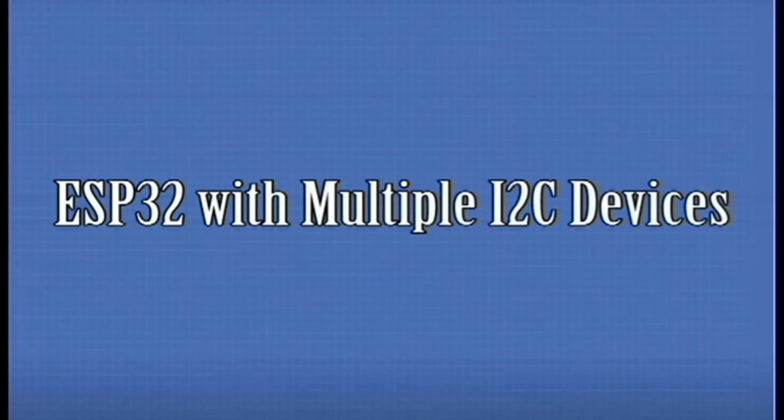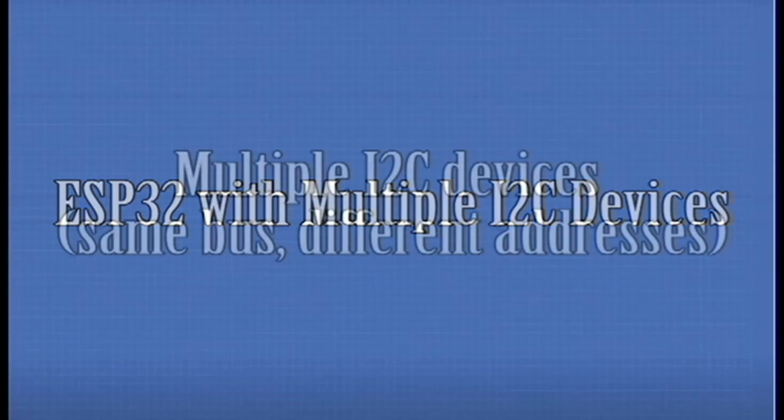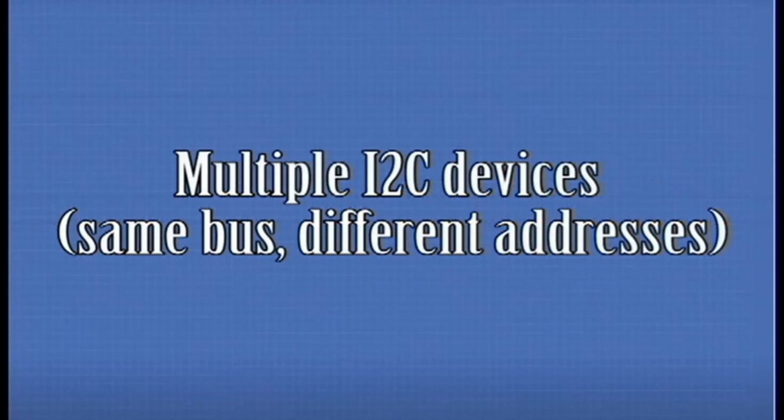ESP32 with multiple I2C devices. As we've mentioned previously, each I2C device has its own address, so it is possible to have multiple I2C devices on the same bus. Multiple I2C devices, same bus, different addresses. When we have multiple devices with different addresses, it is trivial how to set them up. Connect both peripherals to the ESP32 SCL and SDA lines. In the code, refer to each peripheral by its address.